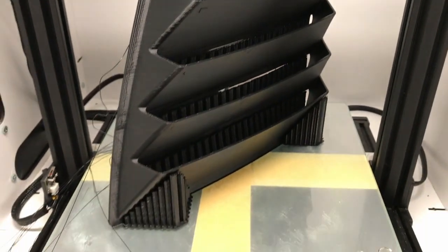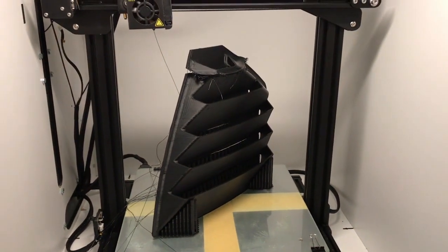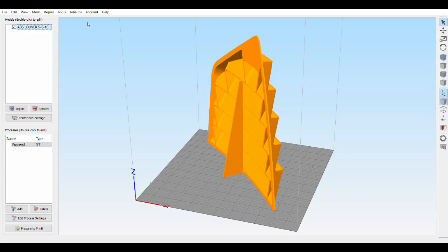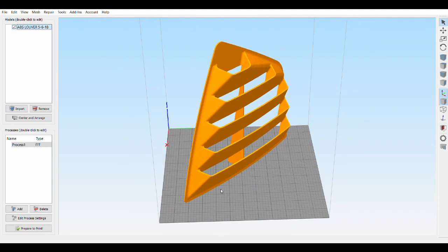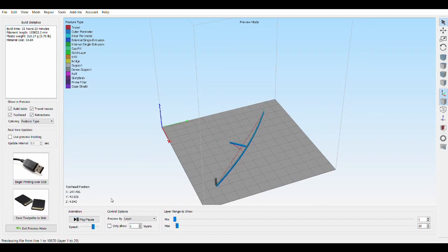I wasn't sure at first what caused this, but I decided it was due to the higher ambient temperature of the enclosure causing the original parameters that I used for the model to fail. I adjusted a few parameters and decided to add a removable stabilizing fin to the back of the model to decrease the chance of vibration. The stabilizing fin worked like a charm and the print was a success.